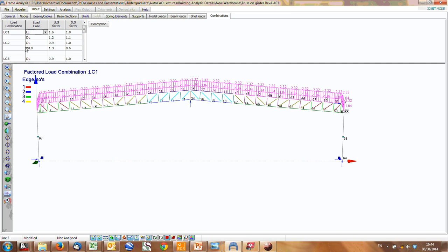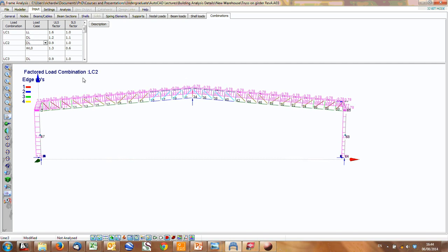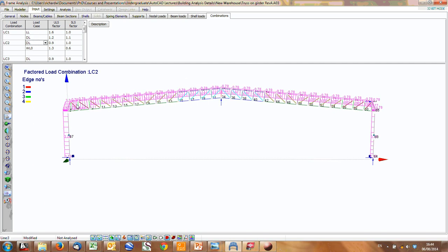We have our load cases here with dead load, live load, etc. And this will also consider some notional horizontal forces if required, or second order analyses. But here we go. Got dead load and wind load, dead load, wind load, etc. So you've got various wind load combinations we consider here. These serviceability ones I just put in there to assist design, so you output serviceability forces and reactions, but you don't need to worry about that.